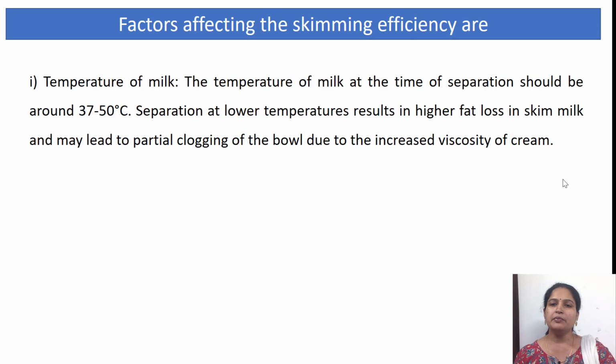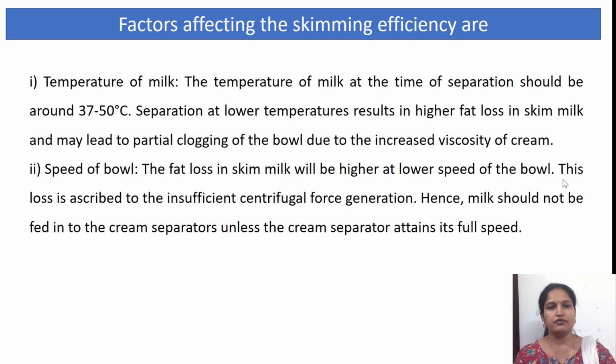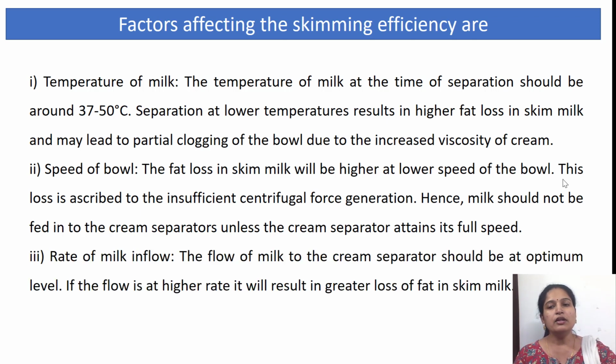Separation at lower temperatures results in higher fat loss in skim milk and may lead to partial clogging of the bowl due to increased viscosity of the cream. Speed of the bowl: the fat losses in skim milk will be higher at lower speed of the bowl. This loss is ascribed to inefficient centrifugal force generation. Hence, milk should not be fed into the cream separator unless the cream separator attains its full speed.